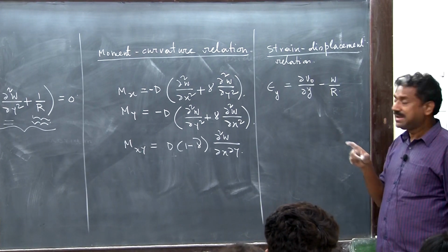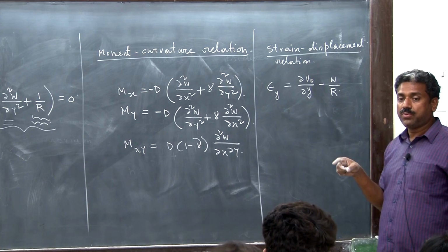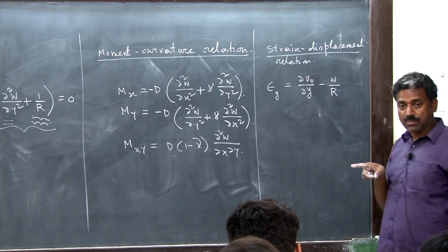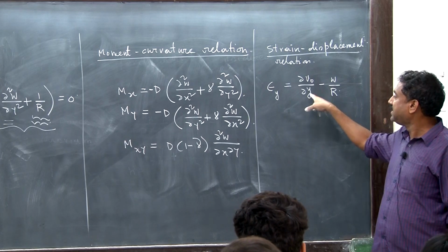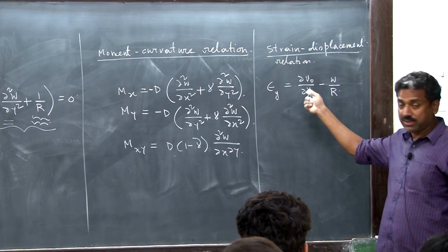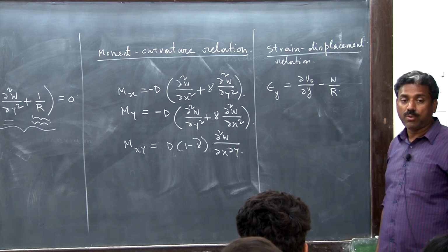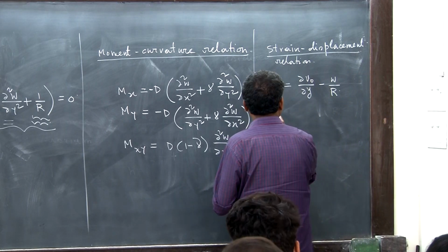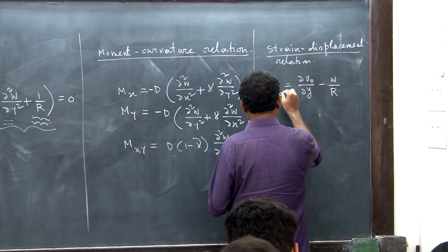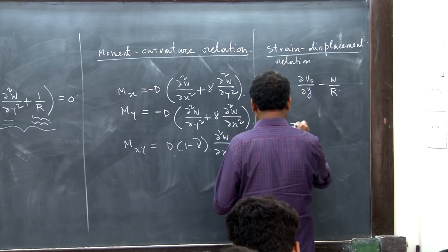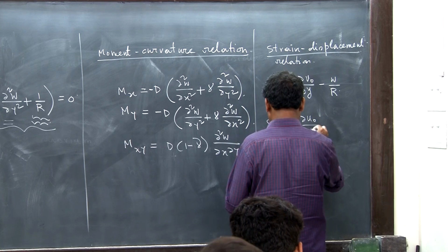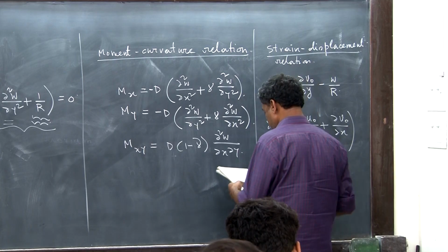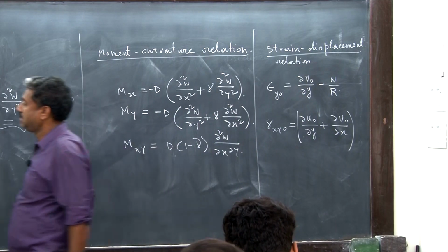So 2 pi R, and then the way this term is coming, 2 pi R plus W minus 2 pi R divided by R. That's what W by R is, with W the out-of-plane deflection, right? And del V0 del y, you have learned from the small deformation theory, right? So this is 0. Okay, so I am removing.